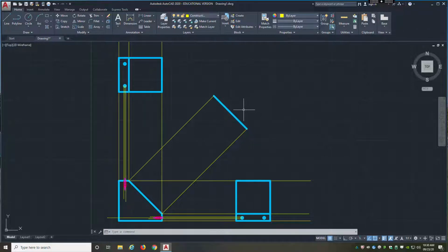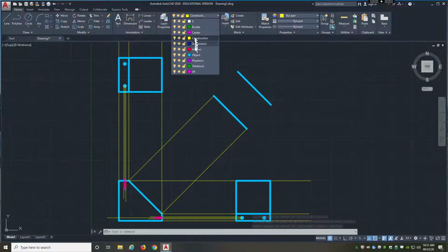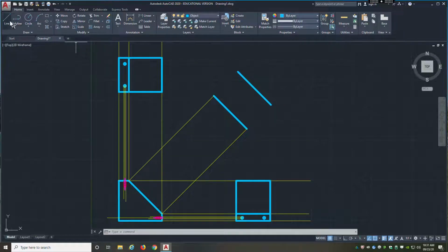And we know, again, we know what the distance is, so I'm just going to use the offset and the full depth of this part, right? We've done it before, 4.250. And I'm going to select this line. There we go. And I can basically jump to my object line and just connect the two so that I have my box. There's one, hit escape and spacebar. Oops, there we go.